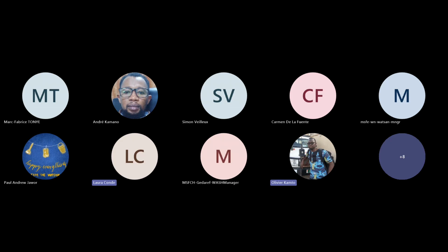Okay, to increase the yield of the borehole, if the borehole is already drilled, it's a little bit challenging. In some instances, if we have a very big diameter borehole, we can consider drilling deeper again. But this is only if we are confident, maybe informed from geophysics surveys, that there may be another aquifer below where we find ourselves.